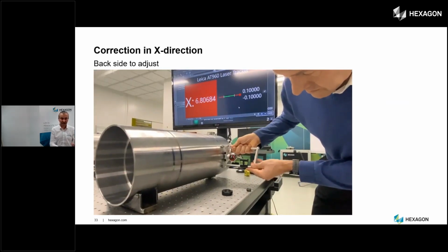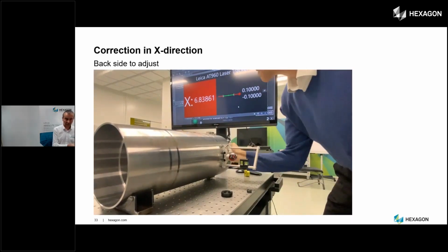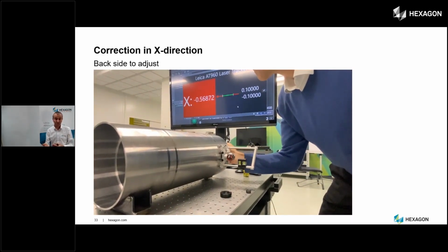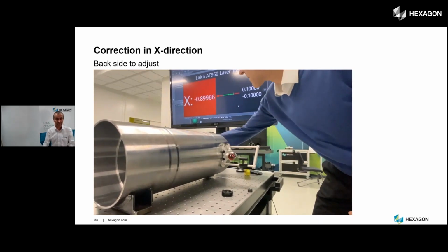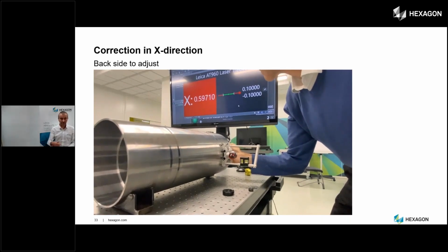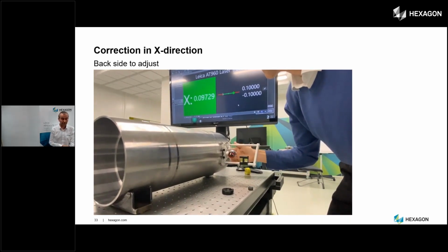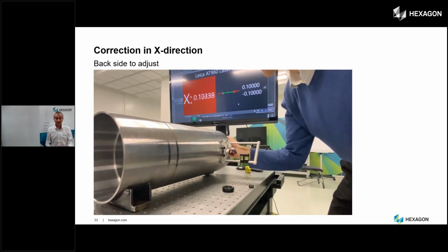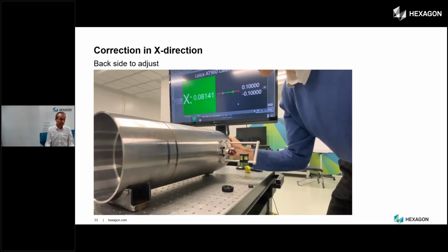Good. So having now set to 0 on the front, putting it to the back end, and then really adjusting the roller with wrenches, with the hammer, with whatever is available, what is possible. Then you see directly on the screen, on your mobile device, on your wrist, iPhone on your wrist, showing the result, just the X coordinate, the deviation, bringing that to an acceptable within tolerance value.